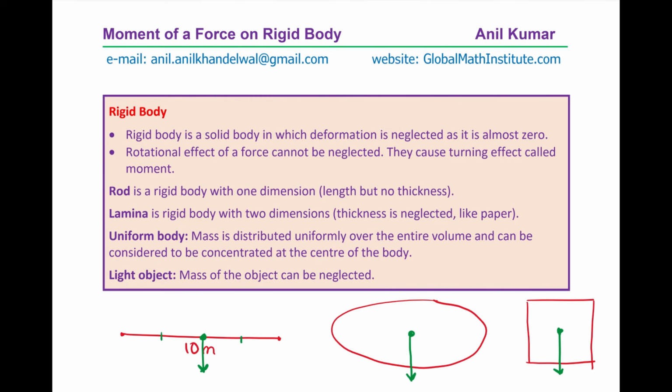You get the idea. Now, let's get into the concept of moment. If I have a simple rod like this, and if I hinge it from this particular point, right? So, if I fix this point, in that case, the weight due to the mass of the object will cause this body to rotate. And in this case, it will be a clockwise rotation, and this clockwise rotation is called the moment, which is the focus of our study today in this particular video. Now, if we have a lamina, which is kind of a body shown here, now assume that I apply a force in this direction. That force F will cause, let us say we have hinged the body right there at the center, this force will cause the body to rotate in the counterclockwise direction. You get an idea.